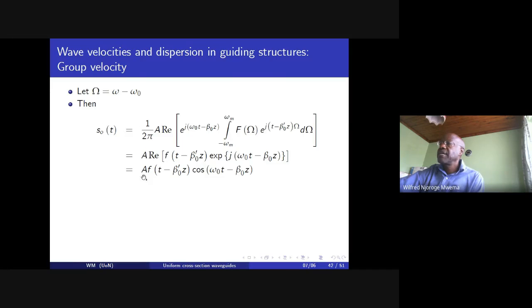It is given by a time delay and a frequency path propagating with the correction factor, multiplied by the carrier signal moving at the center frequency values. So this is a time-shifted replica of the original modulated signal envelope. That is, it's just delayed.